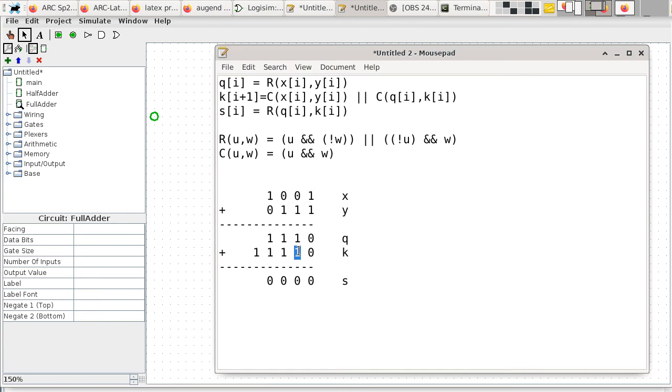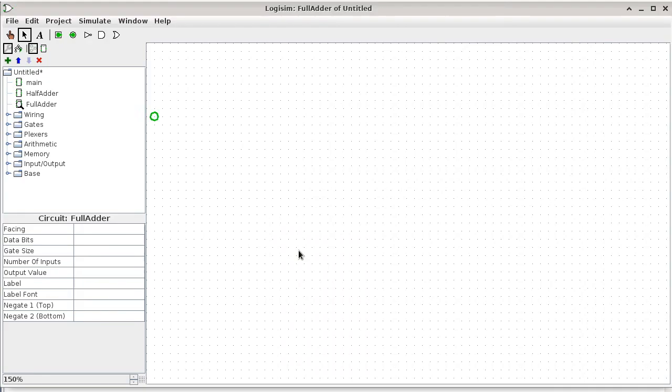Yep. One thing that I'm questioning right now is, is there a way to do this without just chaining a bunch of half adders together? Yes. And that's why we have the carry look ahead mechanism. But I want to introduce carry ripple first so that we can see the problem of this approach. All right, so getting back to LogicSim, I can now implement a full adder using two half adders. Does that make sense? You know, having two halves make a full.